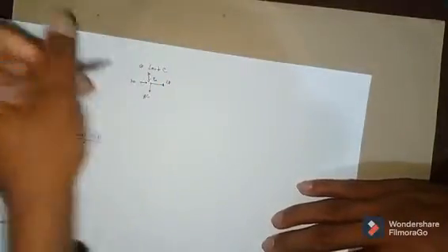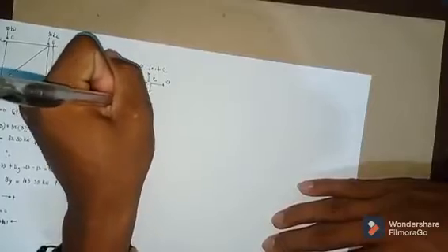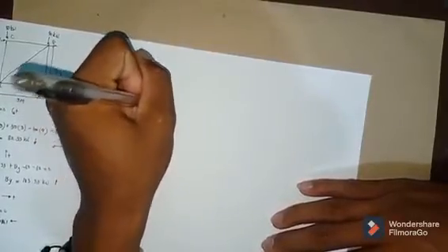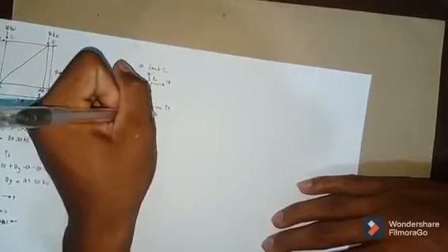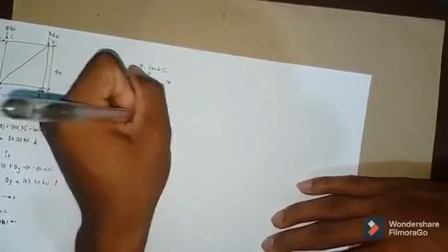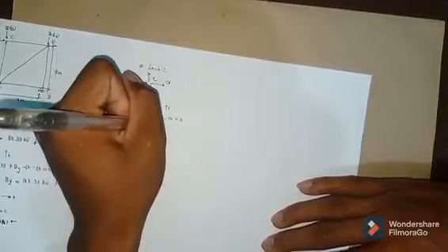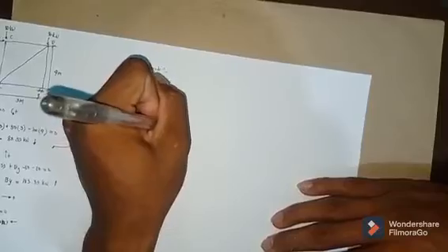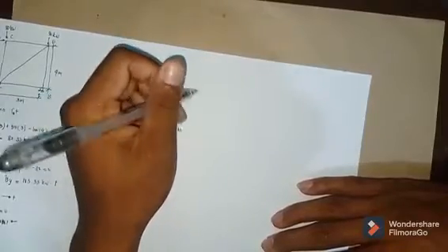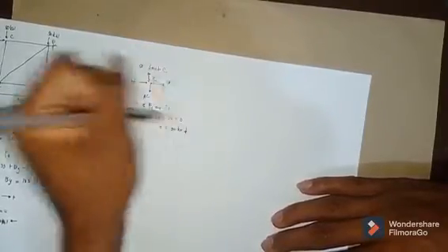So, summation of forces, first, vertical muna tayo. Summation of forces vertical is equal to 0 and all upward forces are positive. So, AC is facing downward. So, negative AC minus 50 is equals to 0. So, AC is equals to negative 50 kN and it is facing downward, which is negative.